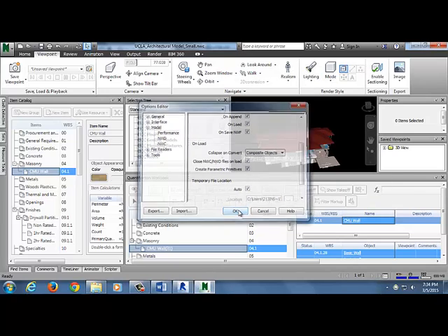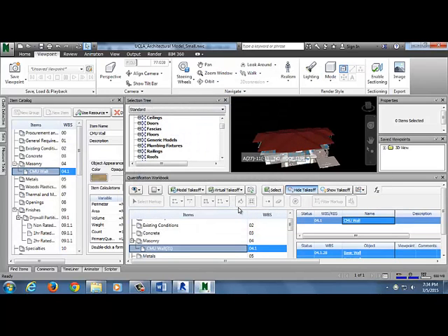Okay? So basically that means, you know how Navis works with an NWF? Whenever you save a takeoff, it's always an NWF. You can't save an NWC. So the NWF is reading your NWC, right? So what this does, it basically just lets you, once you load it, it just creates like a temporary file there, and you could change that, you could close that, you could move it to another location, and you wouldn't mess up what's on your screen.